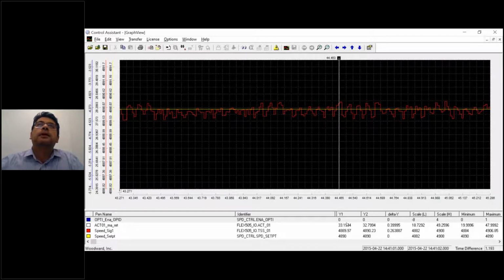That's the maximum RPM that we reach. This was achieved with such low changes basically due to the ability of the adaptive PID tuning to reach the best steady state point for the unit itself. You can also achieve that manually, but that will take hours and hours, and it may take a long time for you to achieve it.